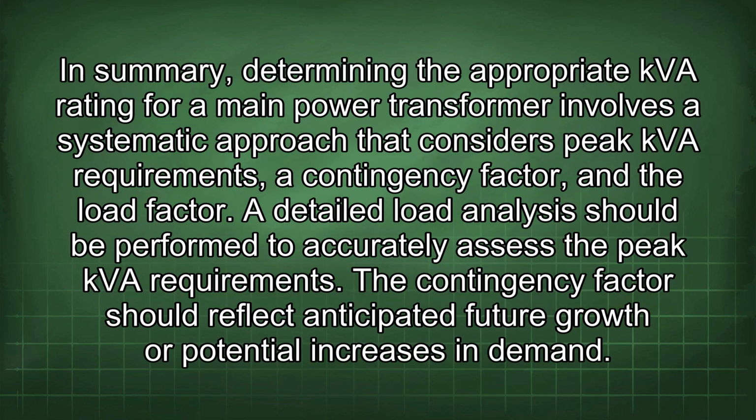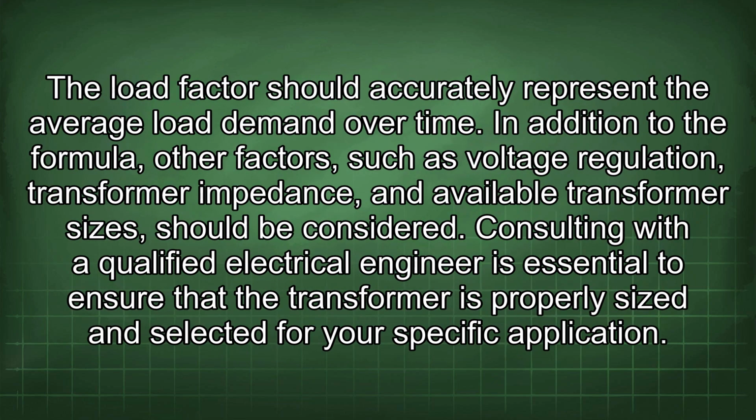In summary, determining the appropriate KVA rating for a main power transformer involves a systematic approach that considers peak KVA requirements, a contingency factor, and a load factor. A detailed load analysis should be performed to accurately assess the peak KVA requirements. The contingency factor should reflect anticipated future growth or potential increases in demand. The load factor should accurately represent the average load demand over time.